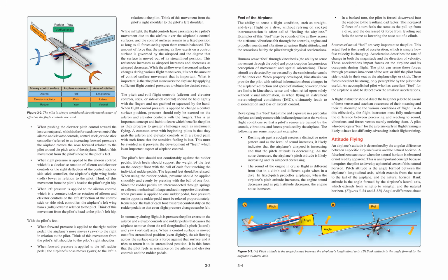Rushing air past a cockpit creates a distinctive noise pattern, and as the level of sound increases, it likely indicates that the airplane's airspeed is increasing and that the pitch attitude is decreasing. As the noise decreases, the airplane's pitch attitude is likely increasing and its airspeed decreasing.